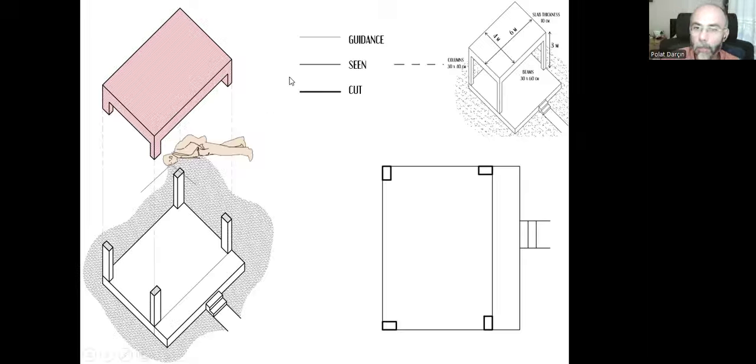So with this middle thickness lines, I am creating dashed lines, the same thickness, same blackness, but not a continuous line. This time, just a line and a gap, a line and a gap, equal lines and equal gaps. And with this same thickness, I can create the sides of my beams. I cannot see them, but I'm indicating them as the projection. And please don't forget the width of the beams is 30 centimeters, same with our columns here.